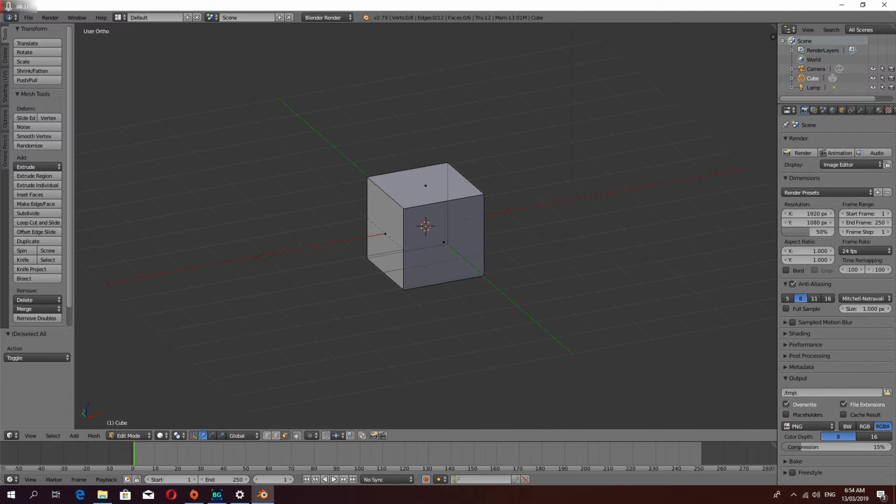But 5 will toggle between perspective and no perspective. Then when you put it in the side views, these are more like what you'd be familiar with in technical drawing. If you've done any technical drawing, you would have these views here. You can also get the bottom view by holding Control and pushing 7.